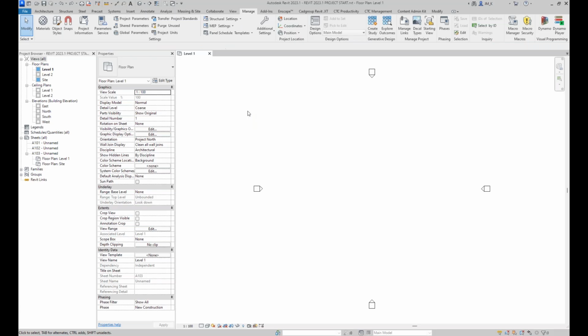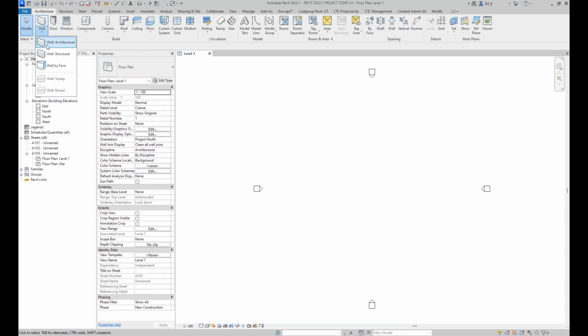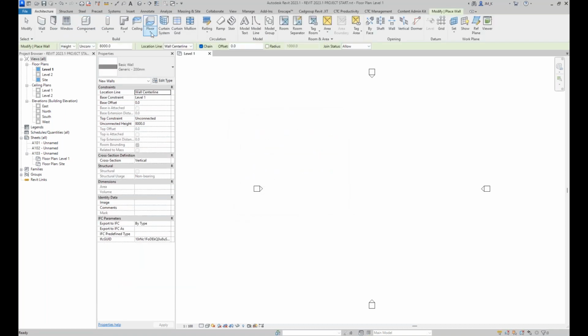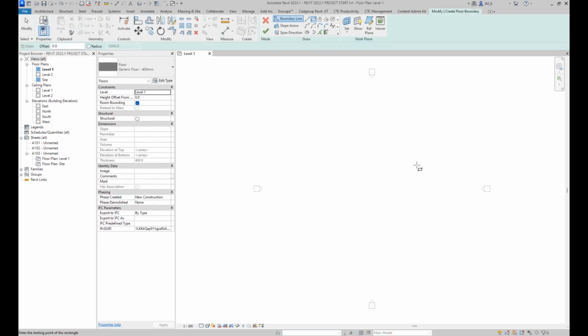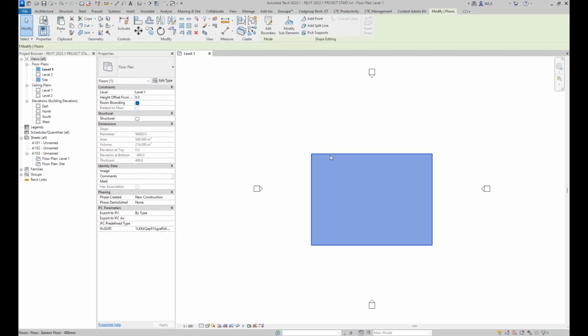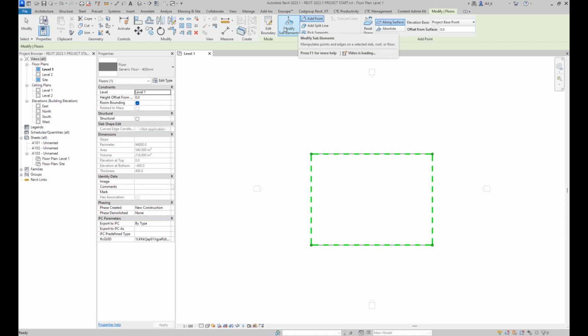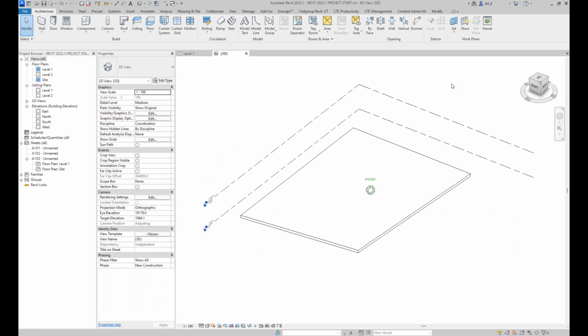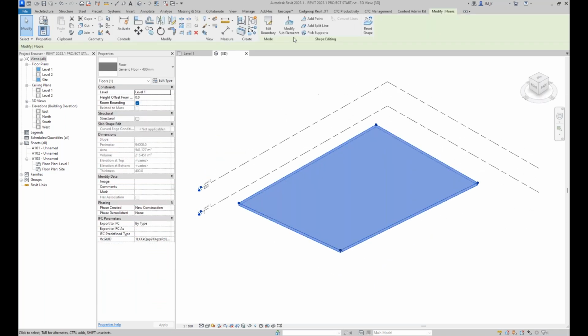So I guess I need to open up Revit at some point here. I'm actually going to open up 23.1. I know you thought you were going to get a 24 demo, but anyway. No, I'm not going to create a wall. I'm actually going to create a floor. And I'm going to then grab that floor. No, I don't want to add a point at this point. I want to modify and grab that one, and I'm going to make that say 1800. Get out of that. Go to the 3D view. I think that's the 1800 one there, right?